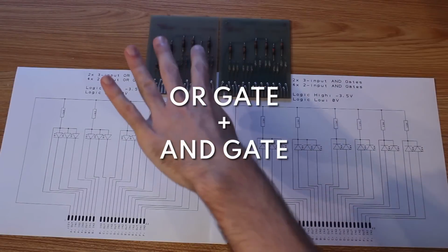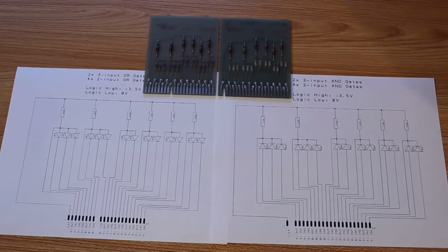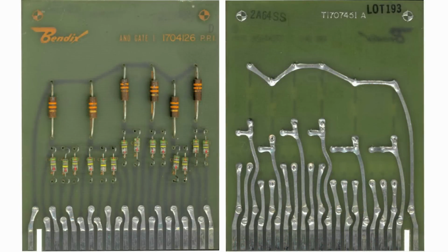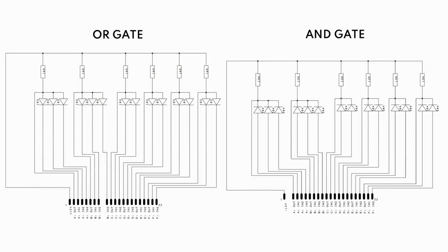All right, so I've got the OR gate board and schematic on the left and the AND gate board and schematic on the right. And well, you can see they're almost identical. As a matter of fact, the only difference that I can really find between these two is first the location of the key here that only allows you to plug it into one particular spot, as well as the direction of the diodes. And if we look at the schematics, well, that points that out pretty obviously for us.